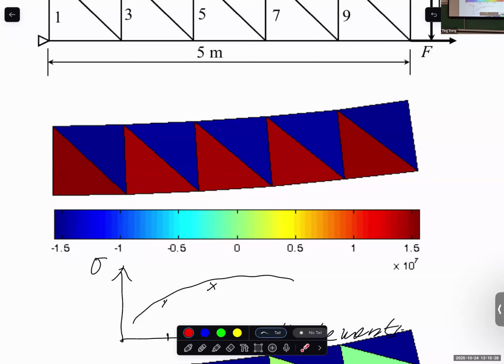Mathematically, we'll talk about this later if we have time. Mathematically, we want the angle between 0 and 180 so that we're able to calculate everything like the inverse and the Jacobian. But Abaqus, when you do plane stress, you can check later, does not allow you to have any interior angle that is lower than 15 degrees or higher than 165.